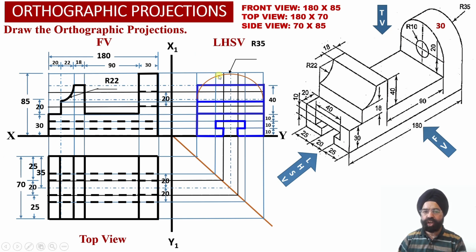So we can check corresponding to this circular arc portion, this portion we will not be able to see properly from the left hand side projections over here. So the hidden line projections will be available into the left hand side view projections over here. Similarly, we know that the height of the top surface of the circular hole happens to lie at a distance of 30 plus 20 plus 10, that is 60 millimeter from the ground, whereas the height of the surface is equal to 70 millimeter.